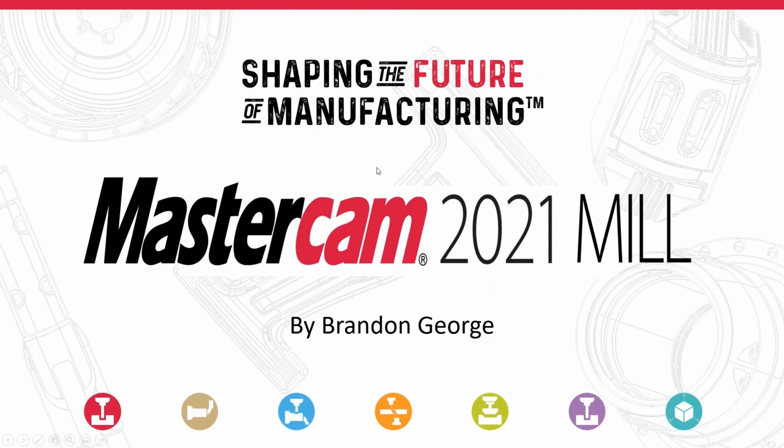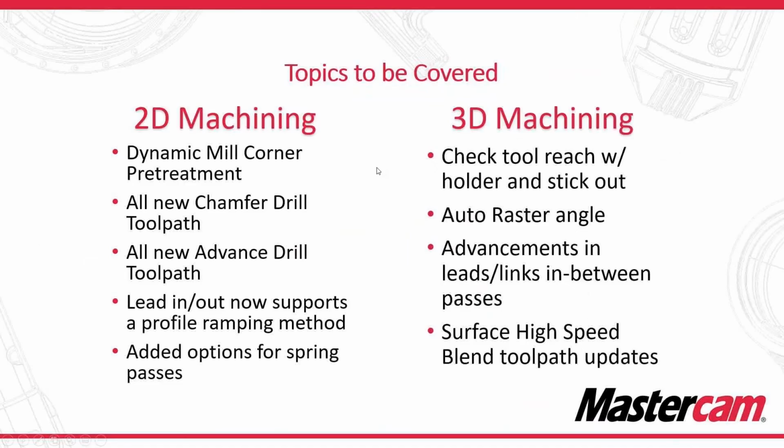All right, so some of the stuff we're going to be covering. We're going to start with all the 2D enhancements in 2021, and then we're going to move on to our 3D after that. So in 2D, we're going to be going over dynamic mill corner pretreatment, a new option found in our dynamic milling. There's two all-new drill toolpaths, chamfer drilling and advanced drill. New options for lead in and lead out for a ramping method, and a couple new added options for spring passes.